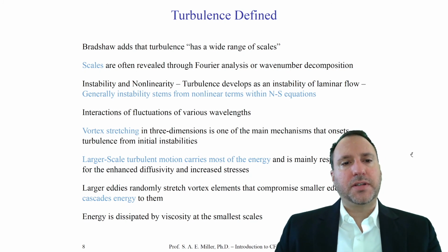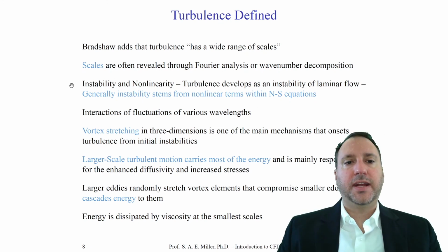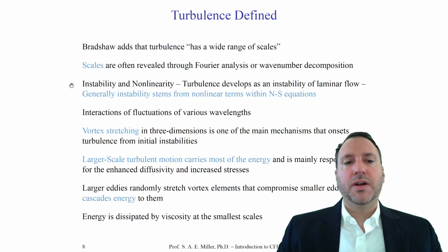Now, turbulence also contains the concepts and properties of instability and nonlinearity. So turbulence will develop as an instability of laminar flow, and generally this instability will stem from the nonlinear terms within the Navier-Stokes equations themselves.